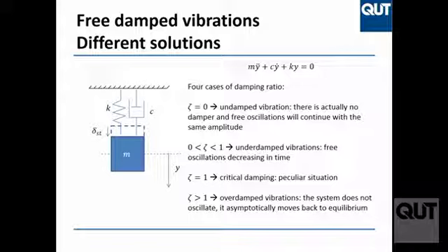Usually damping is very low, at least for a range of frequency which is below 100 hertz, okay? So normal machines, if you hit them and you see how they vibrate, they'll vibrate like this. So vibrate and then slowly damp out their vibration, okay? Like this system here. That's common in mechanical engineering. These other cases happen, but less often.